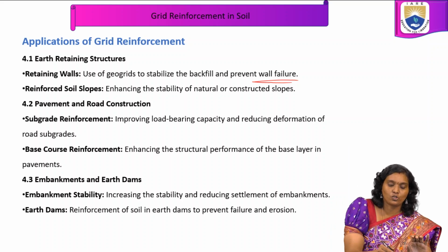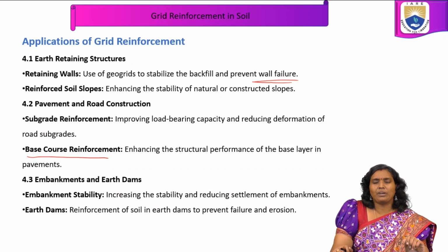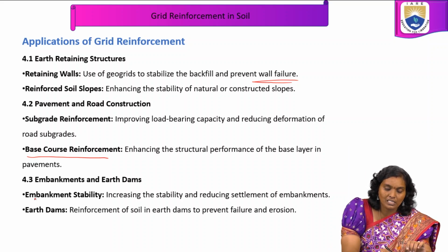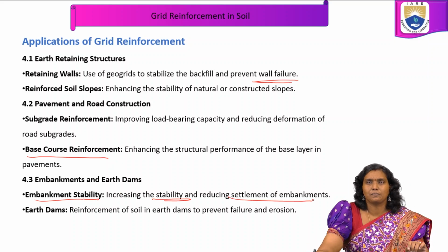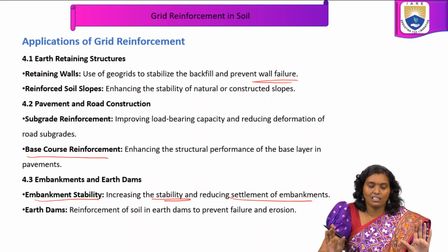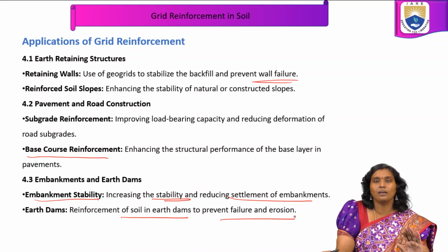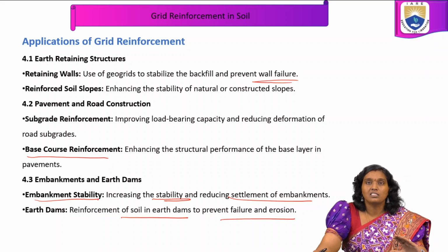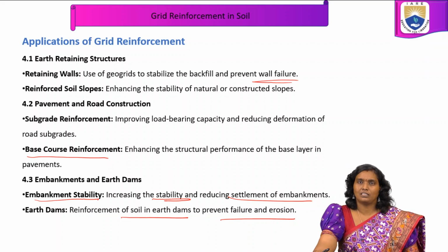In embankments and earth dams, embankment stability is increased and settlements are reduced, so we choose this grid reinforcement technique for the stability of the embankment. In earth dams, soil reinforcement prevents failure and erosion. These are some of the major applications of the grid reinforcement technique.